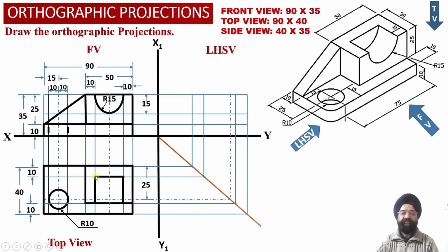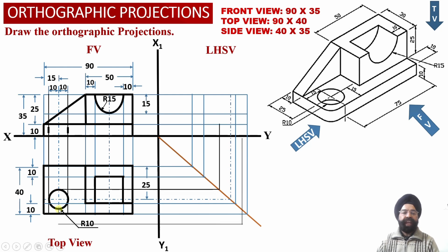Rather, we have obtained apparent shape rectangular projections corresponding to the semicircular slot available at the top surface of this rectangular block. Now we can also see that corresponding to the circular hole, we have to draw two horizontal projector lines using black color into the top view projections, and these projection lines we have transferred into the left hand side view projections.